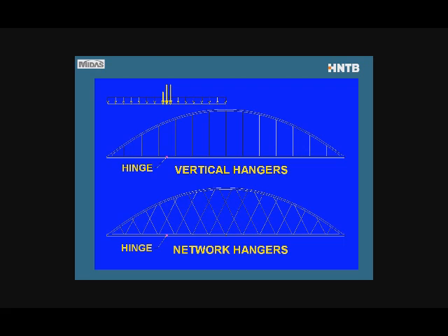Network tied arches, the tie is fracture critical. That means if we lose the complete tie, we lose the bridge. So the tie is crucial to sustaining the load. You can imagine the arch wants to spread out under the weight, and then the tie holds it together, but no tie, the arch will just collapse. Now, what I'm interested in here in this comparison is what happens if the tie is only partially ineffective, say a plate has fractured or something. And so we still have the axial load capacity, but we don't have the bending capacity.